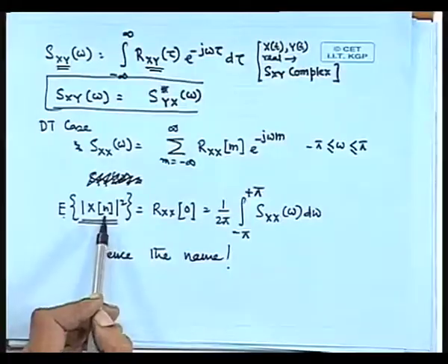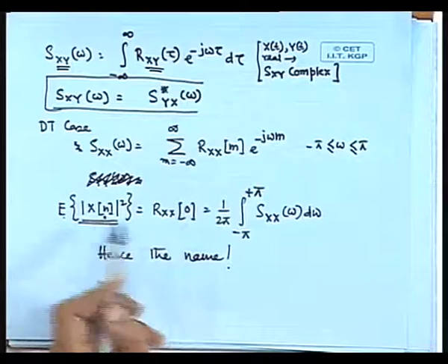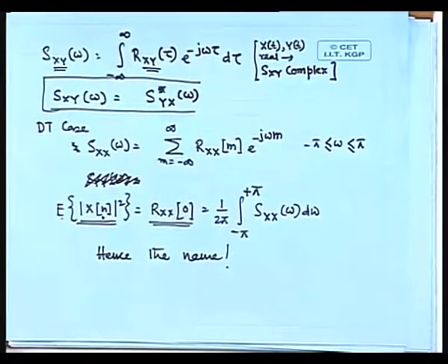I mean, we are not talking of Vi kind of power. We are talking of generally the power of a signal x(t), defined as, especially for a random process, power has a sense of square, isn't it? So if you want to have an expected value of power, then you have to take the expected value of xn square. Now, what is the expected value of xn square? That easily you can find out that it is Rxx(0). Just put tau equal to 0 in Rxx(tau).